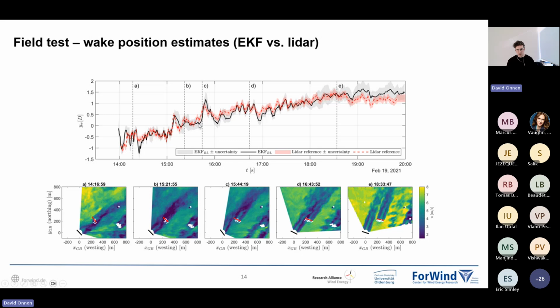At C, we see a large ramp, and we also see some yaw misalignment here. Actually, you have two very different yaw angles of the two turbines, and we also see some expectable wake deflection due to the yaw misalignment. This overlaps with this very steep flank. So we had a yaw transient, and then we see this very steep flank, which was nice.